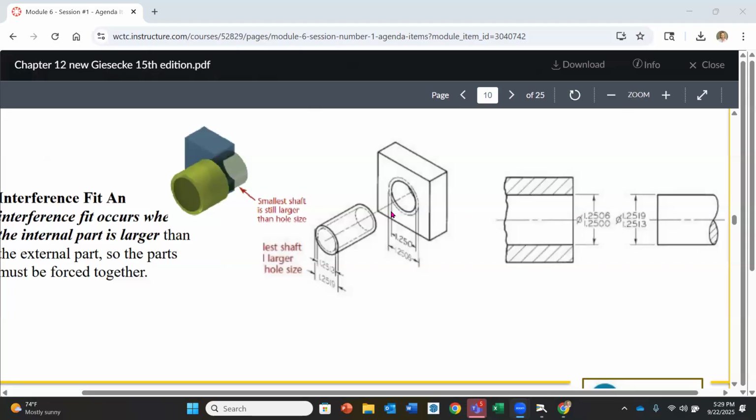Oh, I should have my arbor press in here. It's in the other room that I lecture in. Our second year students modeled an arbor press, and the arbor press physically is in the other room. One of the pins that goes into what we call a table plate stays in there, but it is not screwed in. It's not glued in. It's not welded in. It's pressed in. So it stays in that very same space when they are together as a function. So it's an intentional fit.